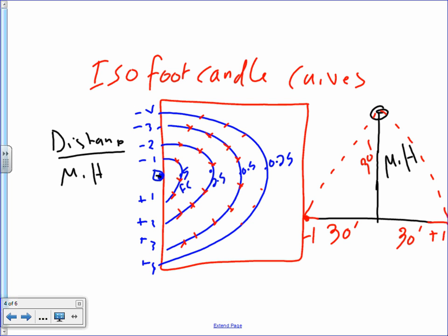Look at this. I have a metal halide fixture, right? Look at this, metal halide fixture. And I have a 30 foot pole. And I did the calculation based on 30 foot on this side, 30 foot on this side, and basically, if you imagine a light in the middle of a parking lot, 30 feet pole, and you're going to do the calculation on every point, a circle of 30 feet around that light. No, it's not directed, it's just a globe. It shoots light everywhere, in every direction.